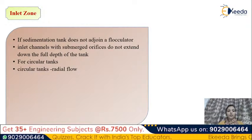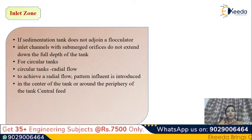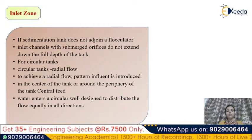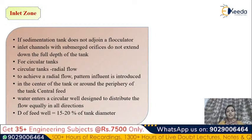In case of a circular tank, the radial flow is maintained. To achieve the radial flow, the baffle pattern is introduced. So we already saw that diagram, right? The diagram of the inlet arrangement in case of a circular tank. In the center of the tank or around the periphery of the tank, center feed, the water enters a circular well designed to distribute the flow equally in all peripheral directions, and the diameter of the feed well, that is the diameter of the centrally placed vertical pipe, is 15 to 20% of the tank diameter.